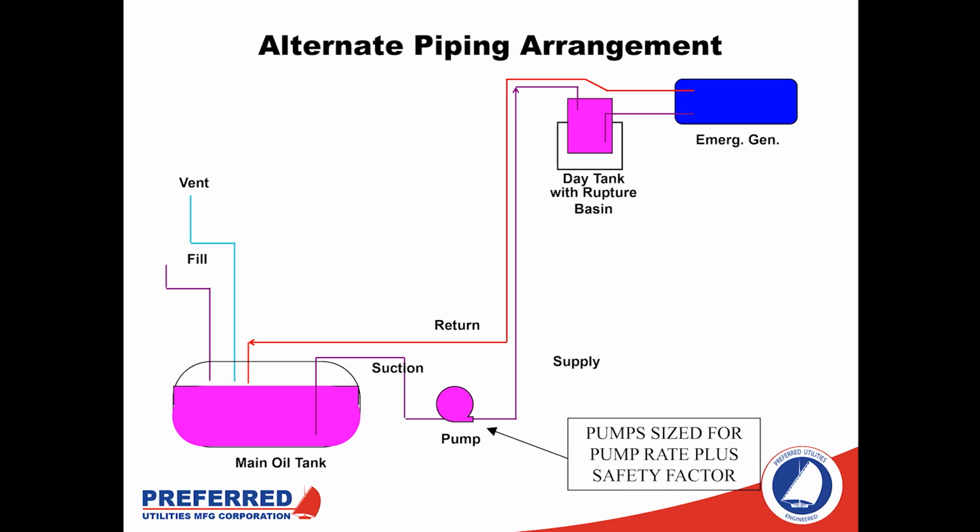The problem here is that now we need a supply pump that is much larger than what we had before, because the onboard pump on the emergency generator itself is circulating 2 to 3 times as much fuel as the actual burn rate. So that needs to be supplied. Now, if we're in the design phase, this can throw an additional monkey wrench into the equation, because we don't necessarily know early in the design what the flow rate of that onboard generator pump is. We'll know the kilowatts or the megawatts rating that we're designing, but we can't use our general rule of 7 gallons per hour per 100 kW anymore. Even though the consumption is known, the total circulation is not known. And with this piping arrangement, that is the factor that we need to design from. So it's an important note to take and an exception to some of the rules that we laid out.